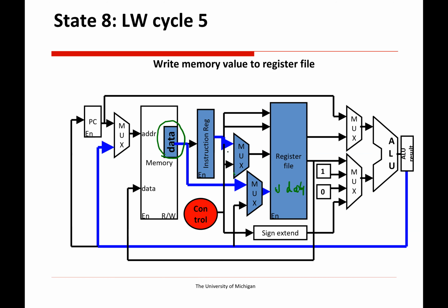So that's why we have this mux in the first place. We're choosing between those 2 bit fields. We're using the top one here, so we need to set that mux to 0. This mux is taking whatever we read from memory, so that's going to be set to 0. That's the data that we're writing.